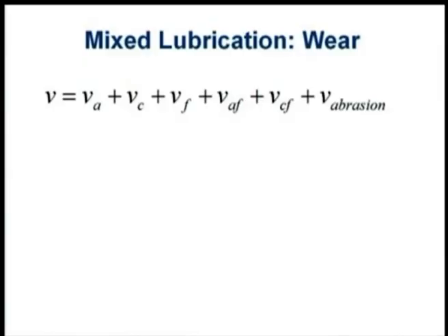Now we will come to the wear mechanism, wear in mixed lubrication. It is interesting. The first and fundamental rule says that wear will never occur because of one mechanism on its own. Only one mechanism will not finally lead to failure. It is always a mixture of mechanisms which will cause the final wear.